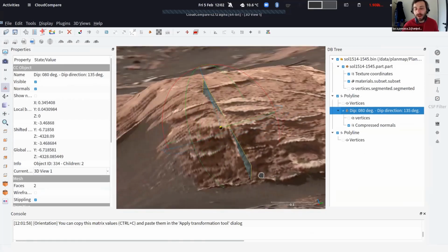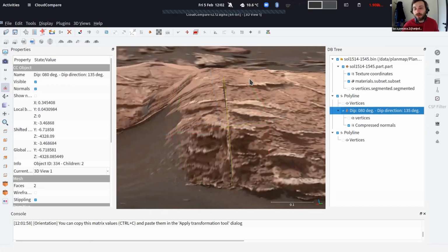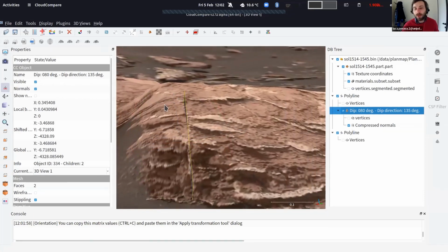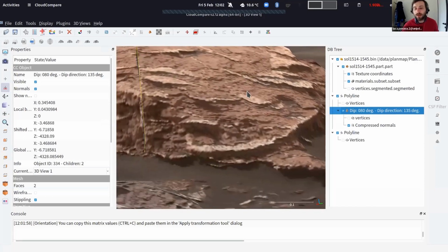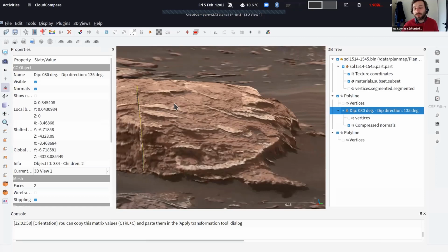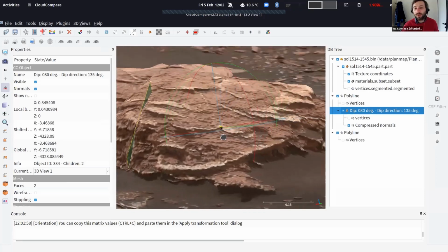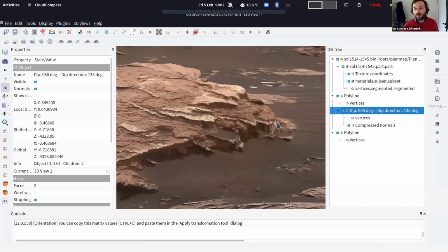and you see we created the best fitting plane passing for that line, right? Of course, this has limitations because if, for example, the polyline is taken on top here, where everything is flat, that will be very difficult. So my suggestion is to always look for planar geometries that you can trace on at least two faces of your object. So just look around, like for example, let's see this one.